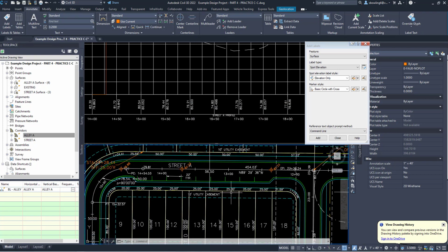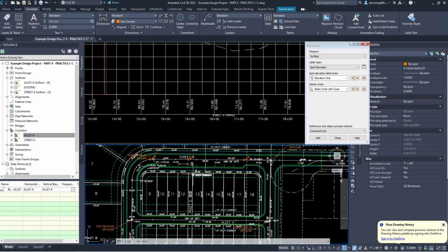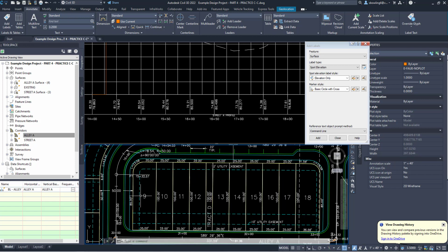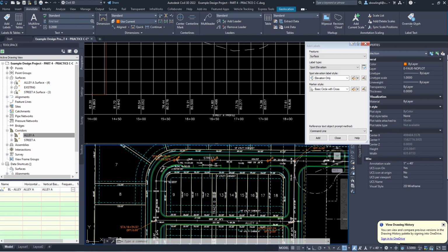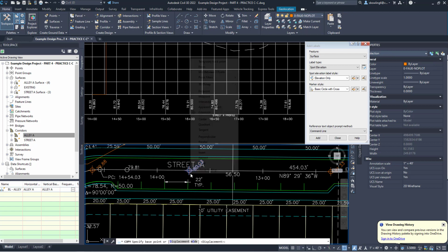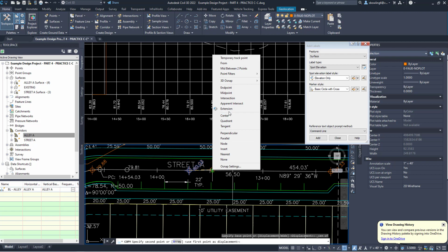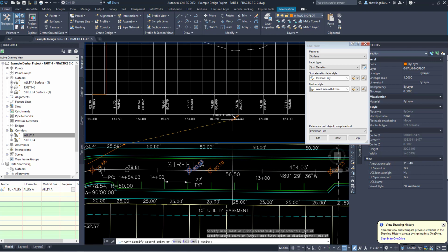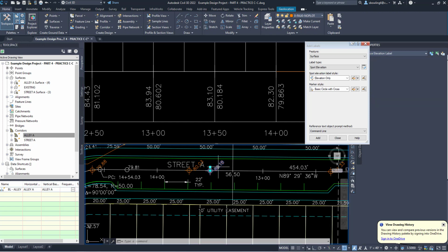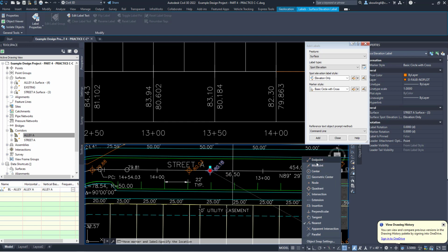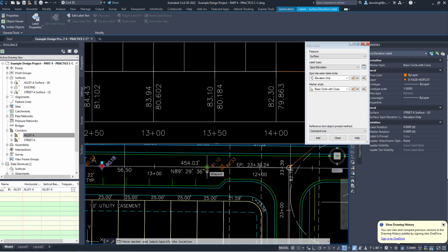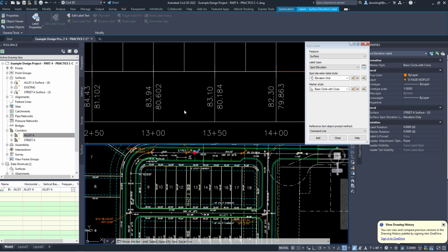All right. Now, so that's going to give me the elevations here on street A. So I'm first going to look at the finished floor of my buildings. So my building is basically going to encompass this block right here. All right. So I am going to also make sure, I'm going to copy this. From the center, I just want to double check to make sure my information is correct. So at 13.50, 80 point, okay. So I feel good about that. And let's move this down. I'm going to do midpoint to here, 18.60. Let's look at 12.50. 81.10. Okay, so I feel good about my surfaces being accurate now.